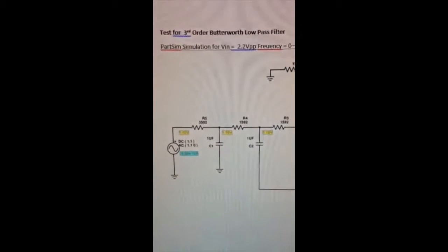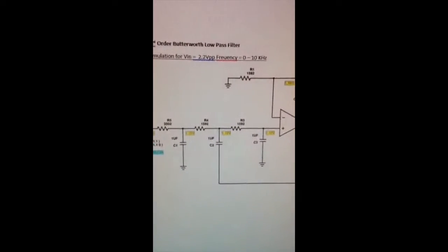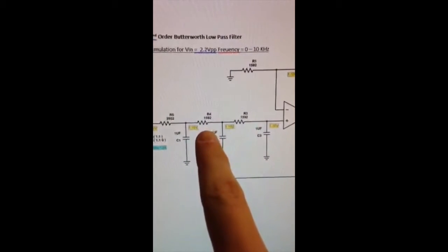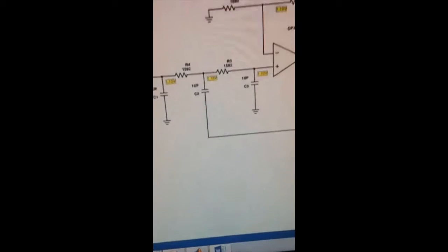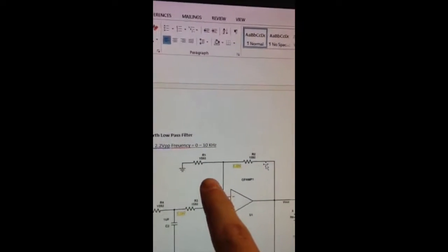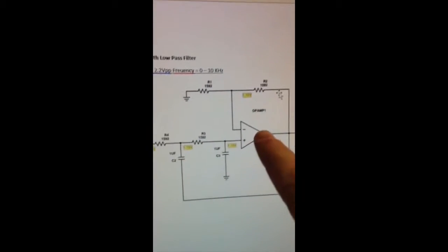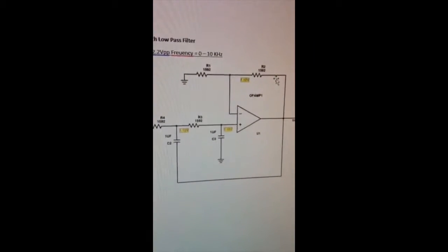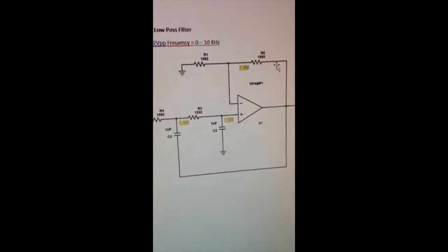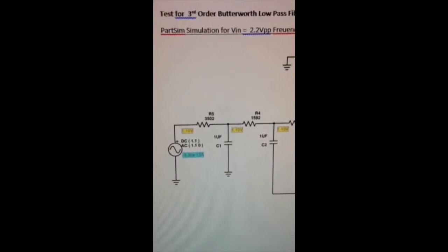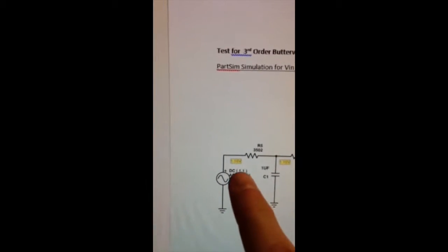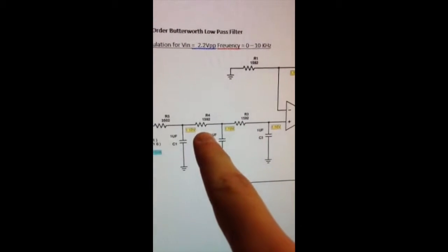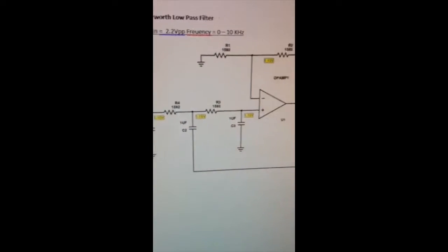All right. And so what we have here is calculations. What we ended up with is about 1600 ohms for each resistor. Up here we have a 1600 to 1600, so a 1-to-1 ratio. We want to keep that. The only thing we had to change was our initial op-amp. We had a Chebyshev filter. In order to correct this and make it a third order Butterworth, this first resistance we multiplied by 2.2 times the typical resistance that we've been using.